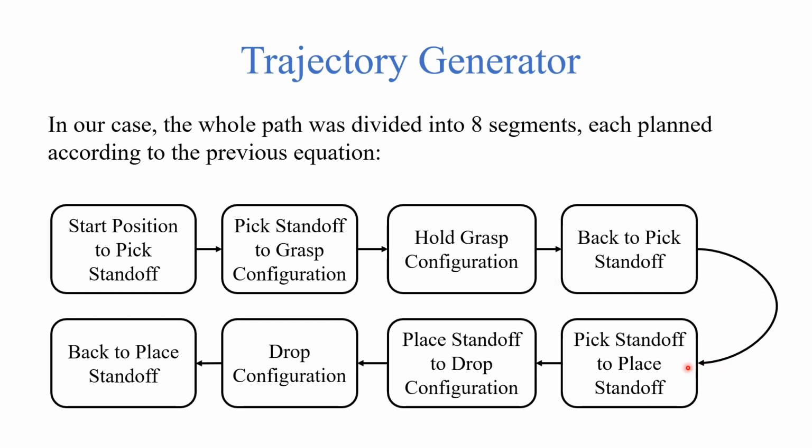From the standoff, we move to a place standoff, that is to the configuration right before dropping the object. Then we descend from the place standoff to the drop configuration. We drop the object and wait for a few time steps so that the gripper fully opens. Then we return to the standoff.